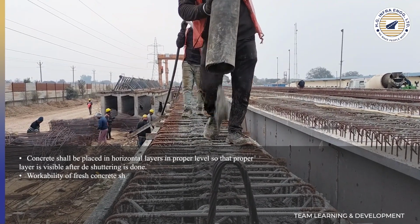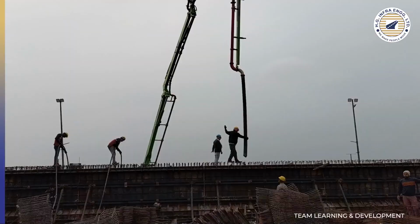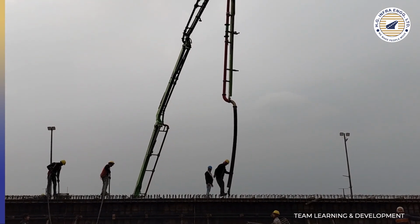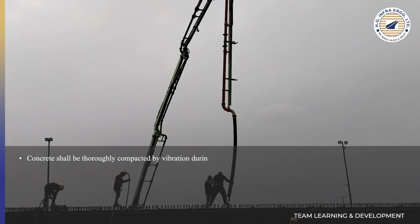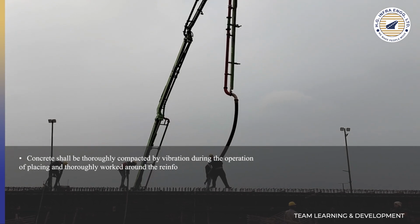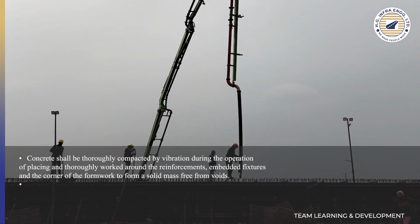Workability of fresh concrete shall be checked before commencement of concrete at the pour location, and if found improper, then modification needs to be done by adding admixture. In case the slump is reduced, concrete shall be thoroughly compacted by vibration during the operation of placing and thoroughly worked around the reinforcements, embedded fixtures, and the corner of formwork to form a solid mass free from voids.